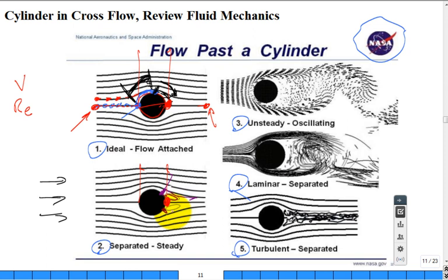And so as you increase the speed, the Reynolds number goes up. Those vortices, well, basically those recirculation regions, will become oscillatory, and they'll pop off, and then you'll have a trailing sheet of vortices being shed off of the backside. Then as you continue to do it, the point of separation continues to move further up, and you can get a very large wake region now.